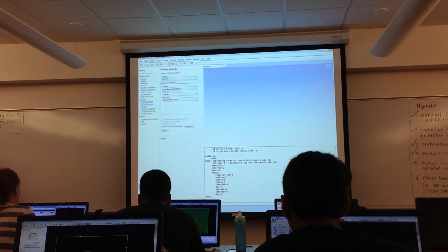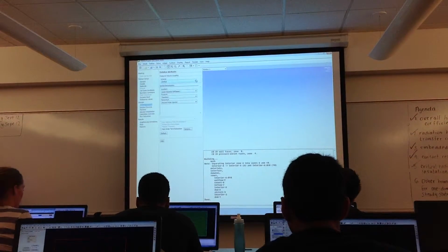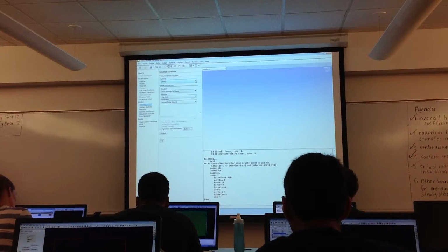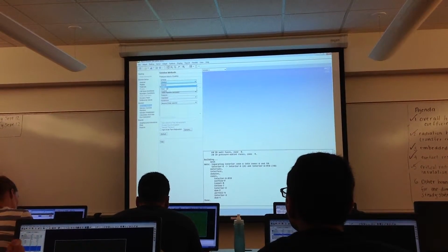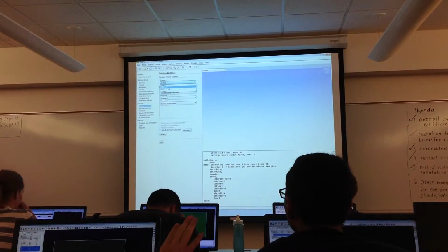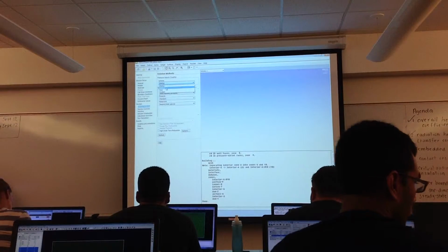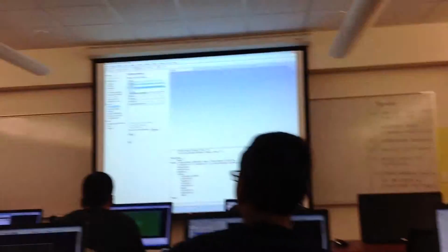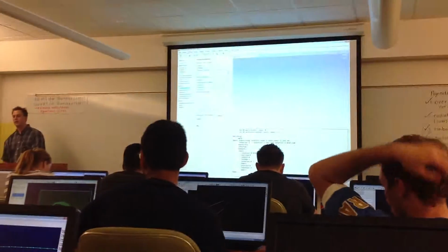Now we're going to this next category, solution. There's different schemes. We're not going to get into the details of how these work in this class. Maybe at the end we can talk about it. But the SIMPLEC, I would recommend over the SIMPLE. It's got an extra correction step in it to make it more accurate and converge faster. So consider it a little more advanced. I would go with SIMPLEC.